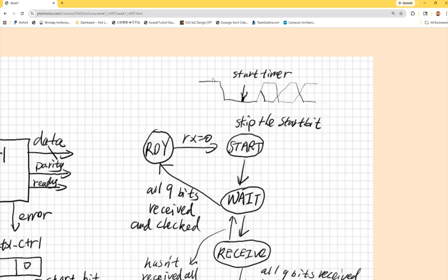And the reason that it should count to half of this total count, or the 1 count per bit, is that if you do it here and then after this state, you keep doing that the standard number of counts per bit, the baud timer, you will be able to sample in the middle of the data, starting from the halfway of the starting bit. Does that make sense?